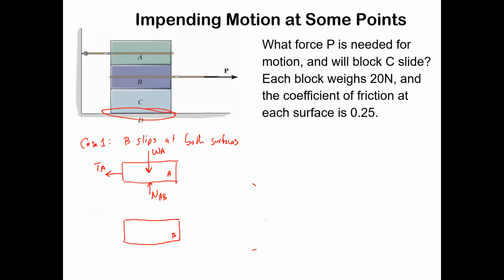The frictional force at the boundary between A and B, right? The friction force wants to make A go which way? When you start pulling on it at P, which way does A want to go? It wants to go to the right, right? What if this rope was loose here? And you start pulling, it's going to get taut, right? Because there's something pulling it to the right, and that force is friction. It's the friction force pulling that thing to the right.